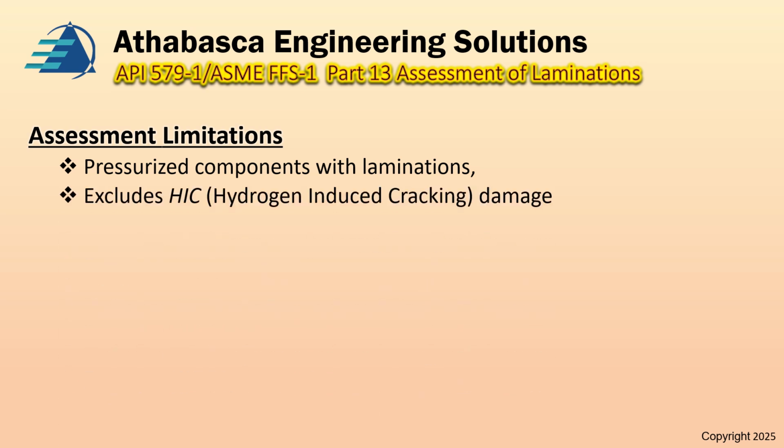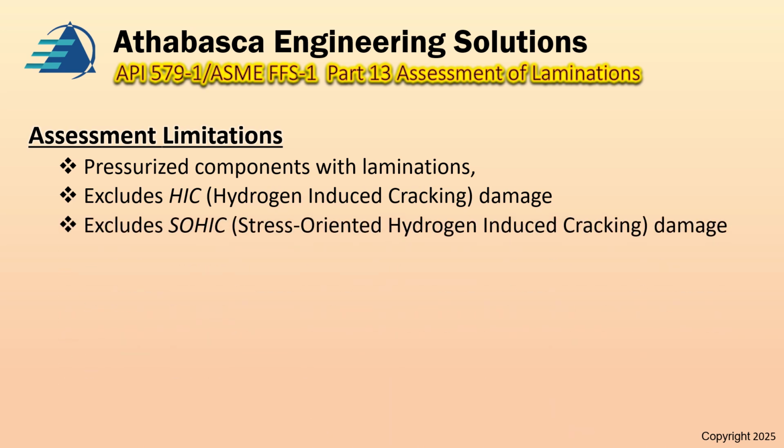The next thing is that Part 13 excludes HIC, hydrogen-induced cracking damage. That's another part in the fitness for service, and we have videos on that. So if you're curious, take a look. It also excludes SOHIC, so that's stress-oriented hydrogen-induced cracking damage.